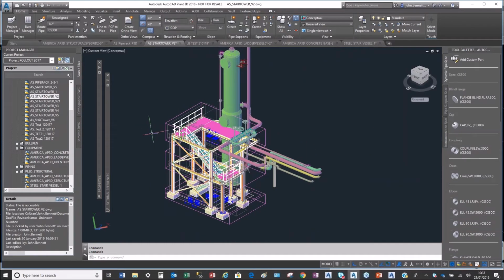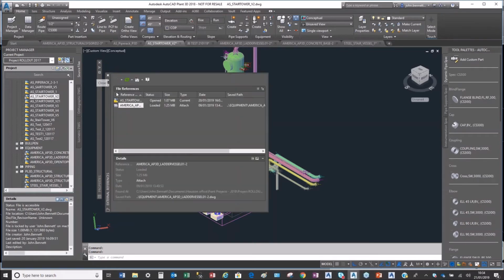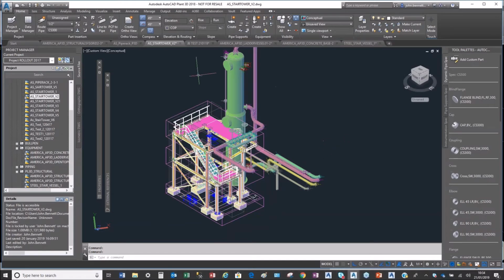So when you're in Plant 3D as well, obviously there'll probably be a requirement to do a drawing. Now, my personal view is that Plant is really good at doing plant, and Advanced Steel is really good at doing steel, with a slight crossover between the two. I would try and do the final structural drawings for the steelwork inside Advanced Steel, but I would do the plant drawings for the plant stuff inside Plant, and I might need to show the steel and the plant combined together. So in this case, you would probably want to create a new drawing, etc.